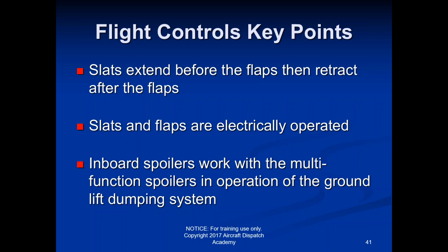It's not fully on the ground until you are down below like 70, 60 knots. So if you're trying to hit the brakes at the higher speeds, it's almost useless, because the tires, if you think about it, don't have weight on them. So braking or even stopping the tires is really not going to do much, because the weight of the plane is still mostly in the air.